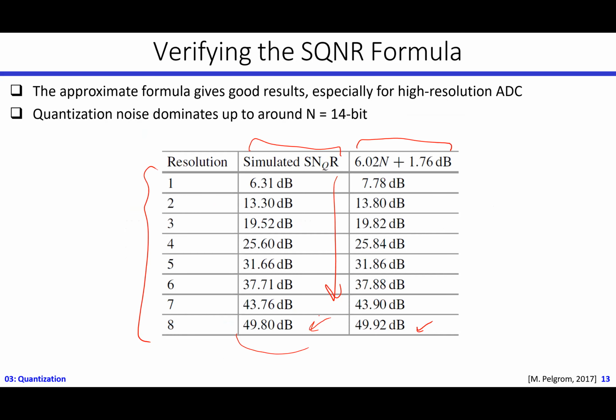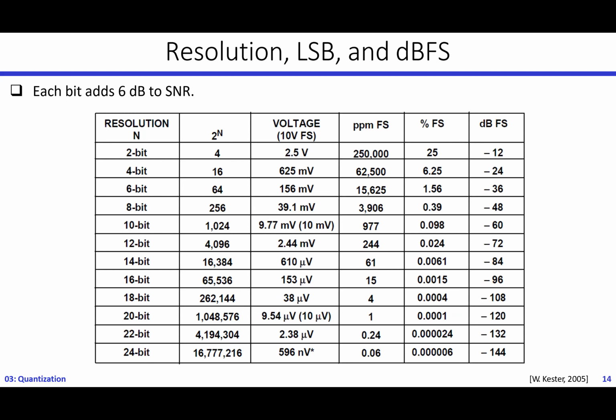Has anyone heard of it? Basically, all the components which I use to implement my ADC have noise. So there is noise that comes as part of my design. For example, the capacitor gives you noise, the resistor as well, and the transistors themselves also have noise.